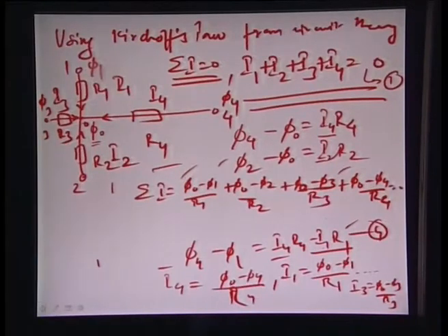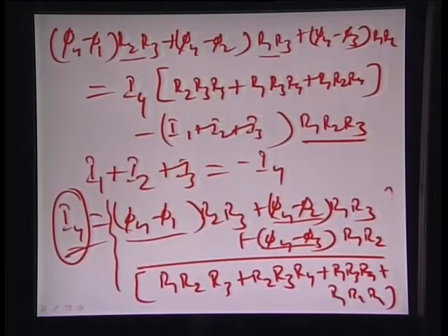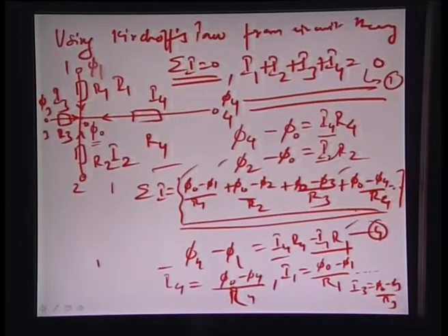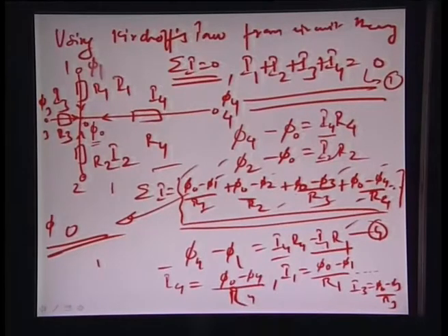So, this brings us to the same equation as we talked about here, where we were trying to calculate what I4 is. Okay. So, this is another very simple method. From here you can find out phi 0, which is unknown, because you have only one variable and one equation. Other parameters, phi 1 to 4 and R1 to 4, are all known, and then from phi 0 you could easily find out what I4 is just by calculating phi 0 minus phi 4 by R4. Okay. So, this is a much simpler method of mathematical estimation in comparison to the other method which was demonstrated.